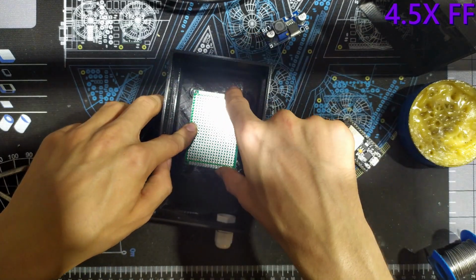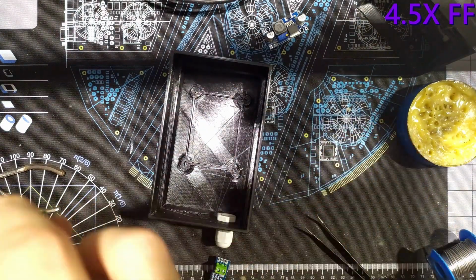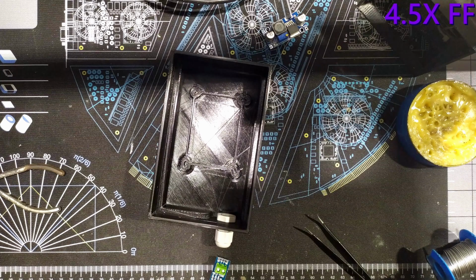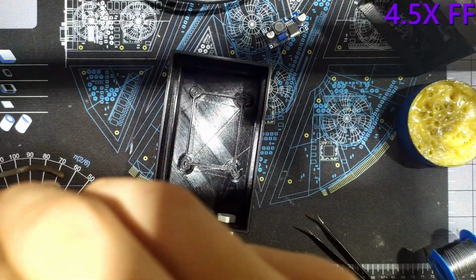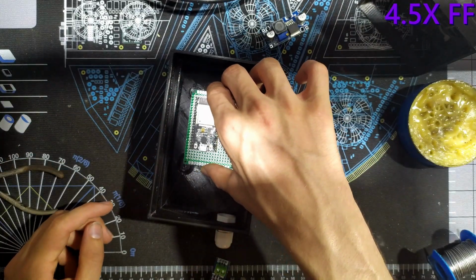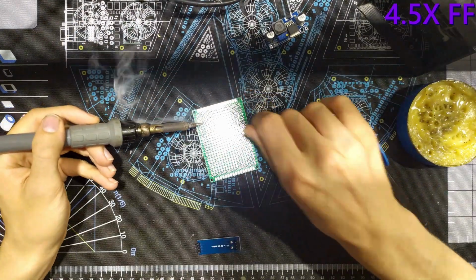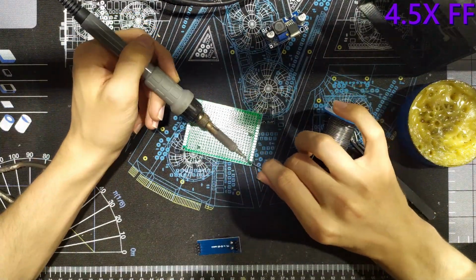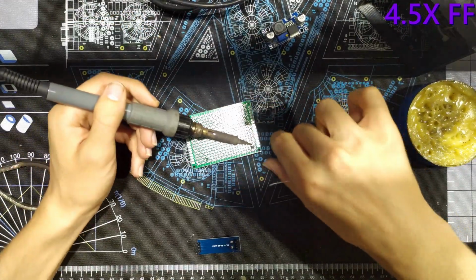So now I have to solder everything onto a PCB and jam it into that box, so I can finally try it out properly. The first thing I did was to make sure the standoffs in the plastic shell actually fit together with the perf board I wanted to use. After that, I had to test fit the ESP32 in place to make sure the pins at the bottom don't clash with the plastic border of the shell. After I made sure everything fits, I soldered it down on the 4 pins on the edges.